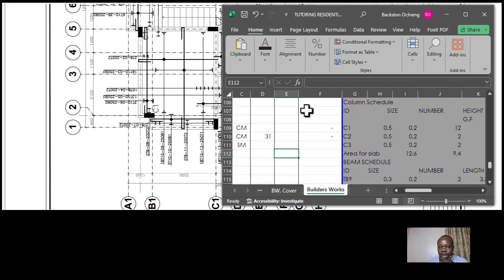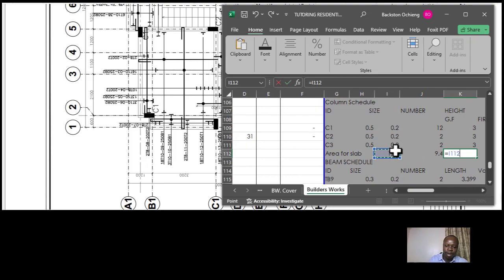Once we have that, we'll take it complete. We multiply this length by the width. Having done that, we need to measure the area net, implying that we take it complete and then subtract those areas which are not forming the slab, or those areas that are going to be considered differently from the slab. Then we multiply by the number of floors which are typical to the one that we've just done. That is the best approach that we can always take to measure our slab.